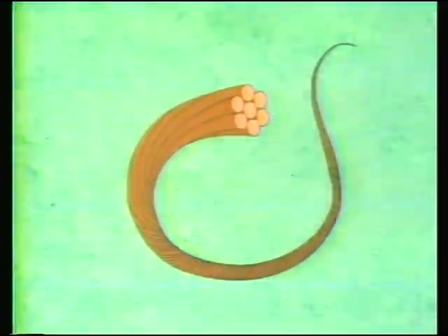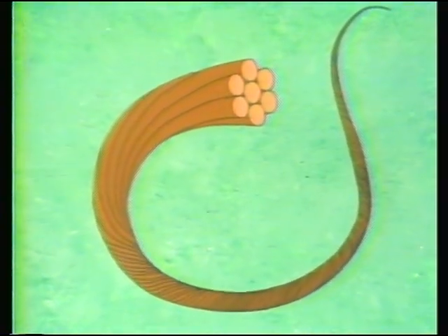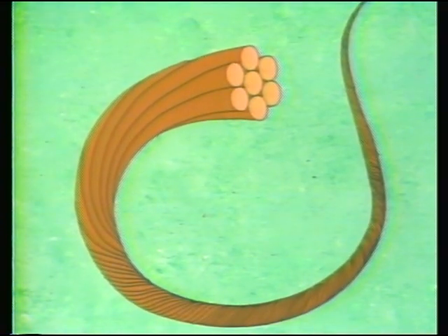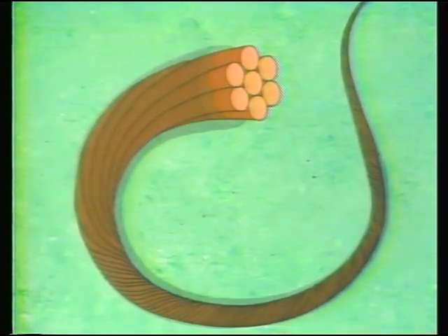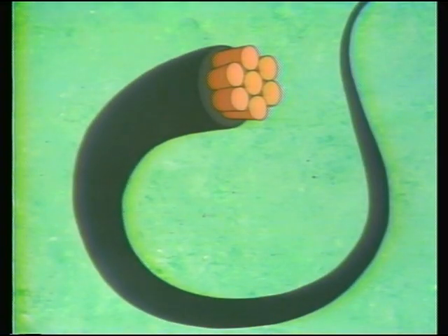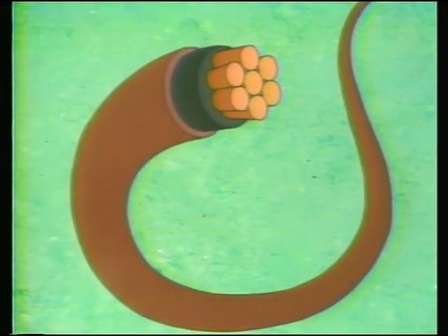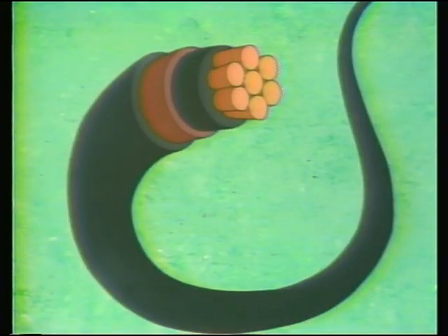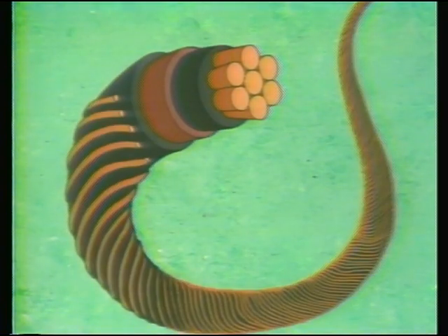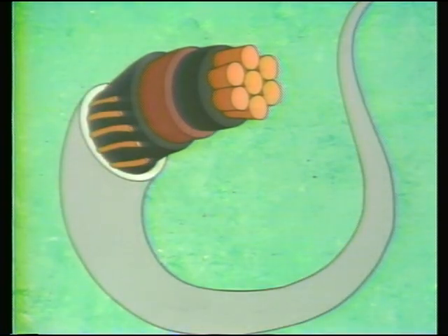For this program, we'll only be concerned with primary cable terminations. So let's look at how a primary cable is constructed. In earlier training, you learned that a primary cable typically consists of a conductor, a semiconductive conductor shield, primary insulation, a semiconductive insulation shield, and a metallic shield. In some cases, the cable may also have an additional outer protective jacket.